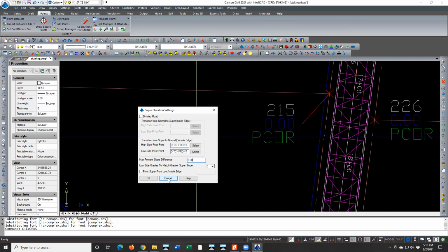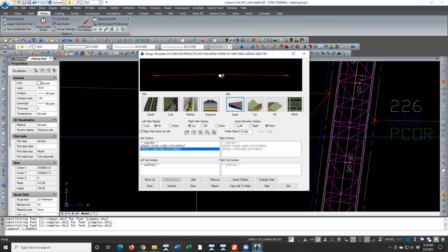Well, you could, but when you transition to center line, this stays alone. This doesn't do anything. So this is the only part that's going to raise is over here. And depending on your super elevation rate, it might need to be 4% instead of 2. So it's at -2, it'll come up to 0, go to 2, and then it keeps going to 4. That means this would be at -2 and then up at 4.